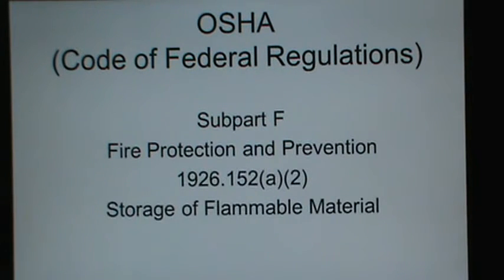Okay, let's look at subpart F still. We're still talking about fire protection and prevention, and we're going to flip over a page or so to section 152A2. And paragraph A2 says that flammable or combustible liquids shall not be stored in areas used for exits, stairways, or normally used for the safe passage of people.